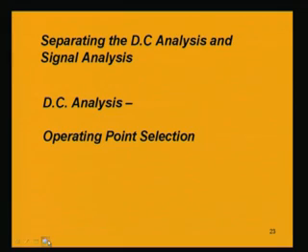So, now the amplifier as such is amplifying an AC signal, and it has a voltage gain given by minus Gm into Rd, Rd being the resistance at the drain, and the minus sign signifies the phase reversal.